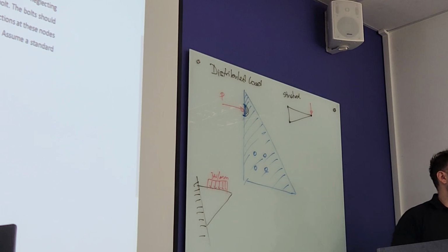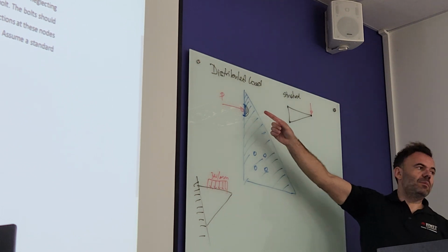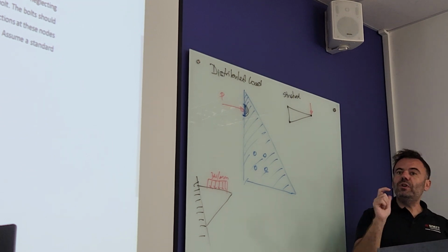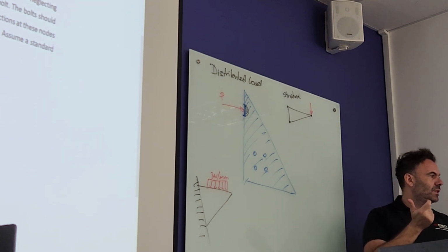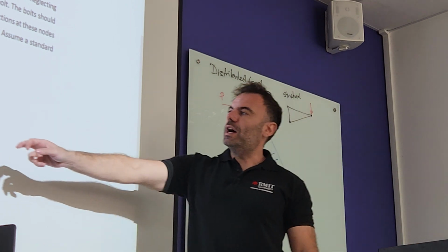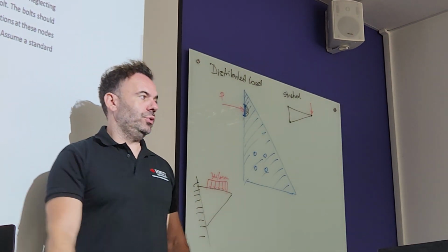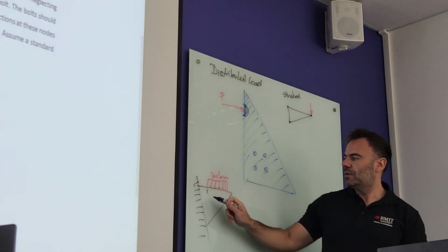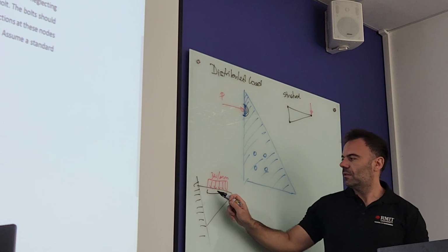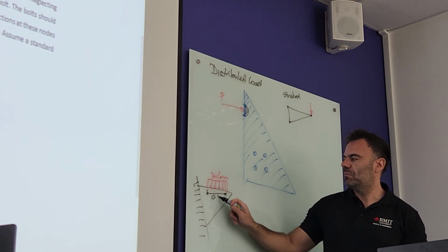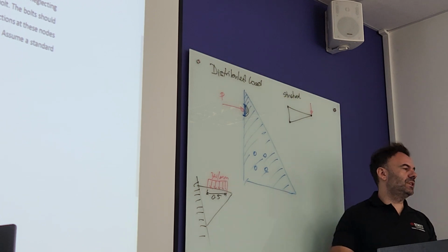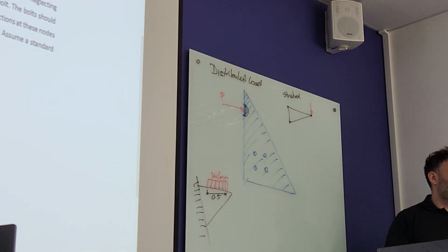That is distributed load. You could apply something like that there, which is more realistic. But again, you have to figure out what values. So if you are to apply a total of 4 kilonewtons and you have a width of half a meter, let's say, what would your distributed load be then? So you have to recalculate that. Yeah?